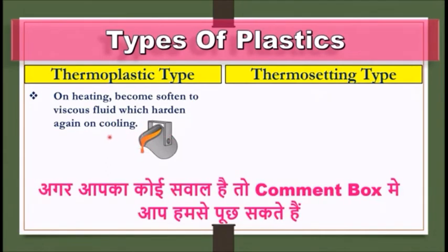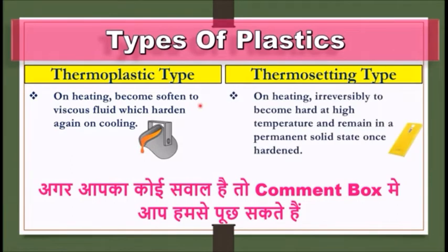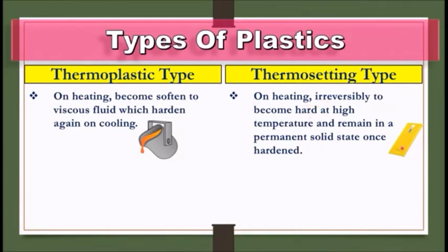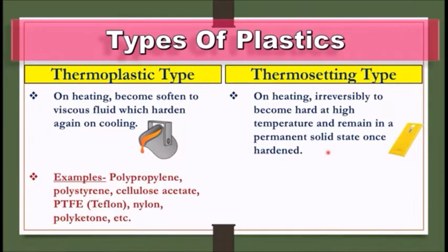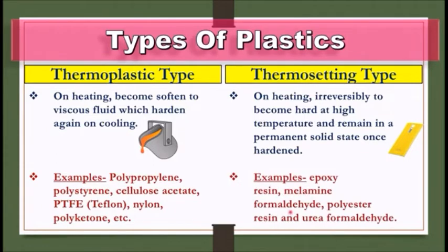Next one is type 2 glass. This type 2 glass, when stored for several months in a damp atmosphere, has condensation of moisture on the outer surface, with salt being dissolved out of the glass in this process. Then the blooming or weathering is characterized by the appearance of fine crystals on the glass, which are washed with water or acids.